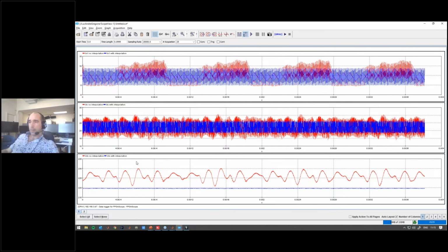Depending on what you want to study, you can say that you have a 5 volt oscillation over 220 volts, so it might not be that bad, and can be good enough depending on what you're interested in. But you have to be careful: if your controller tries to compensate those oscillations while it's running, it might generate even more error. So that's about it for the demonstration.